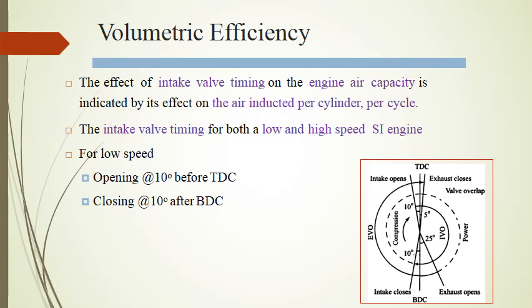High speed engines, however, bring the charge in through the intake manifold at greater speeds, and the charge has greater inertia. As the piston moves up on the compression stroke, there is a ram effect produced by the incoming mixture, which tends to pack more charge into the cylinder. In the high speed engine, therefore, the intake valve closing is delayed for a greater period of time after bottom dead center in order to take advantage of this ram and induct the maximum quantity of charge.